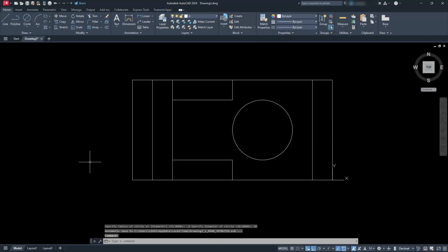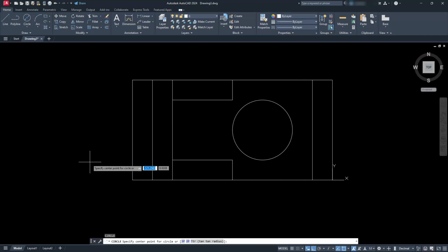So I can go ahead and put that other circle right on the inside of that, and I'm just going to hit the enter button on my keyboard here. That's going to take me back to the last command I used. I'm going to go ahead and type in where I need it to go, and it's going to be 35, 25. I'm sorry, that's going to be a negative value. Let's go ahead and enter again. -35, 25.